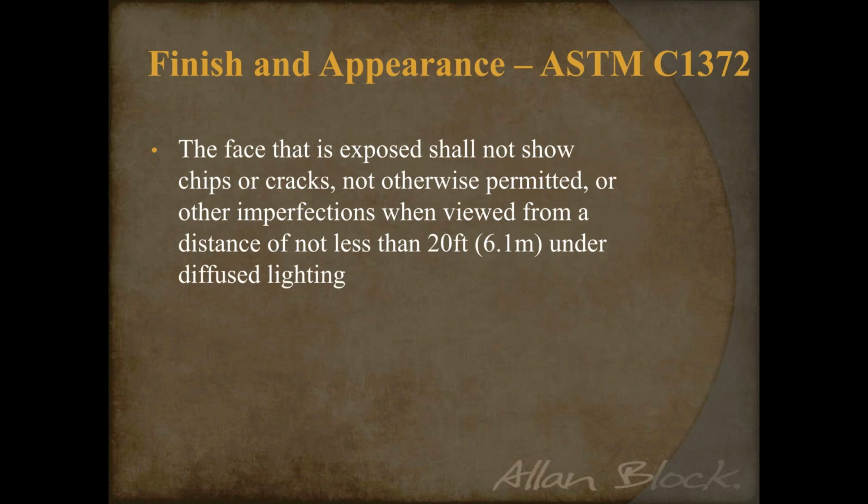Now, I really like this one, and this one is almost word for word directly in 1372. The face that is exposed shall not show chips or cracks not otherwise permitted, or other imperfection when viewed from a distance of not less than 20 feet under diffused lighting.